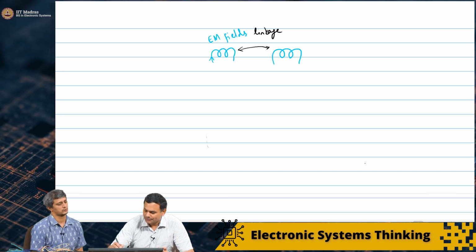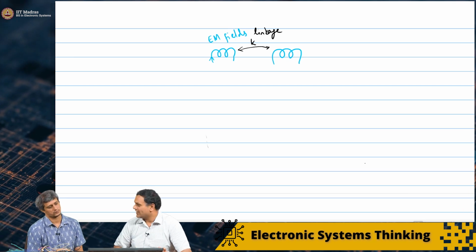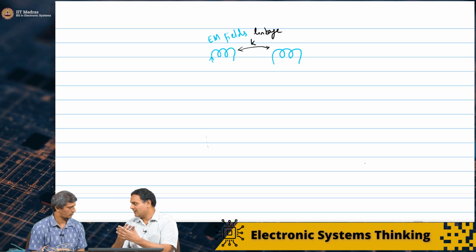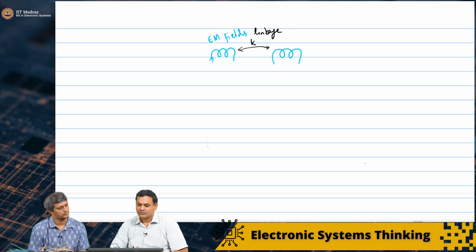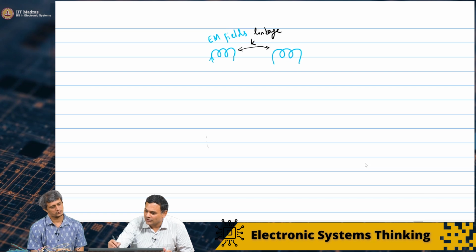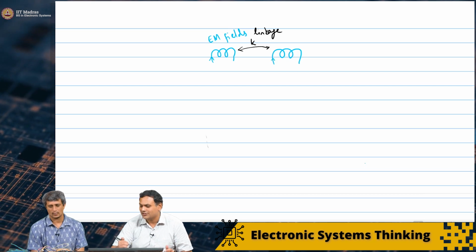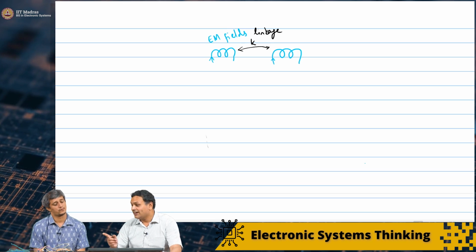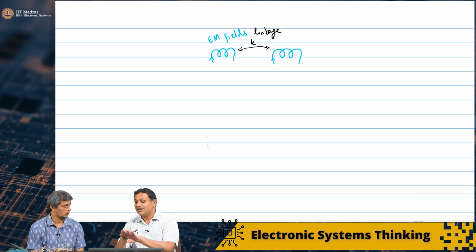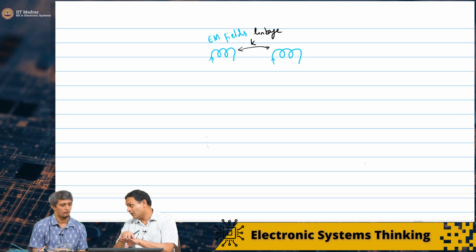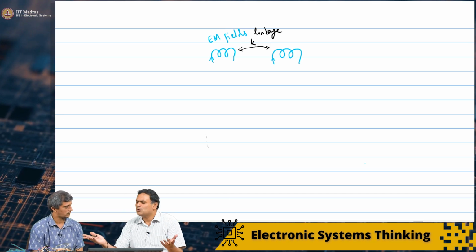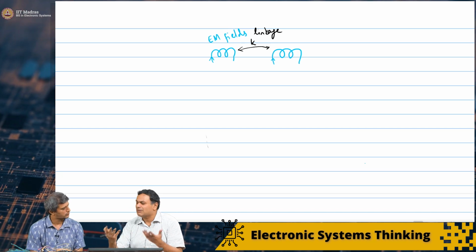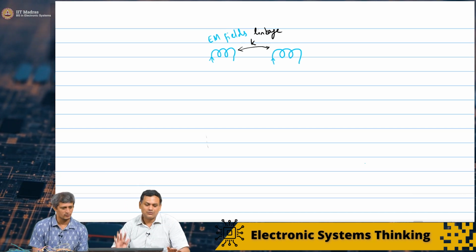Right, which is called some coupling factor, let's call it K. That is what near field communications exploits. That is just a quick introduction to what coupling means. Now, if you place the inductors very close, the coupling will be very strong. The minute you move them even a few inches away, more than 6-7 inches, the inductive coupling should be very slight, low. That's what we are hoping.